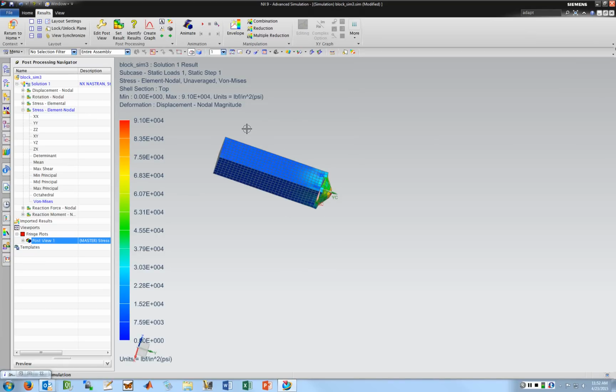For anything that's thick, you really can't do this at all. I mean, so where does that point end? Probably somewhere around 1/10 of an inch is where I would, or just very complicated geometry, I'd probably switch over to doing a full 3D tet mesh. It really depends on the resources you have.